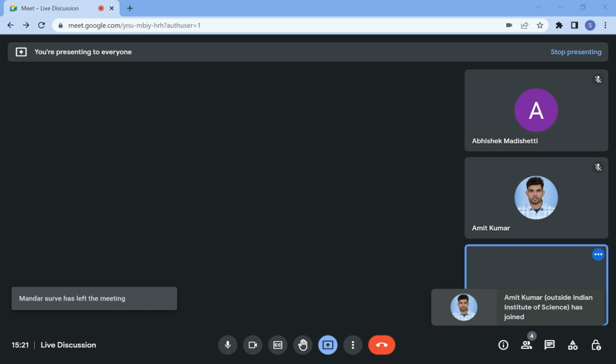So I know they have said that the front view of the line is 50 degrees inclined to XY. So this is my XY. The 50 degrees inclined line I'll draw, and I'll mark 55 mm to mark B. Now again I have got that this is the locus of all the points B.